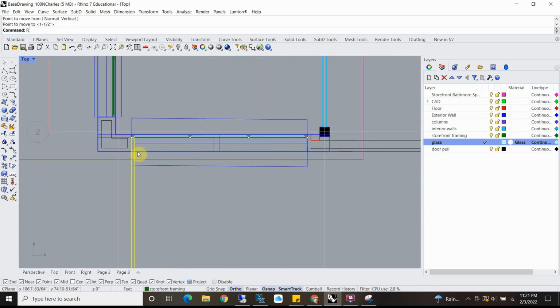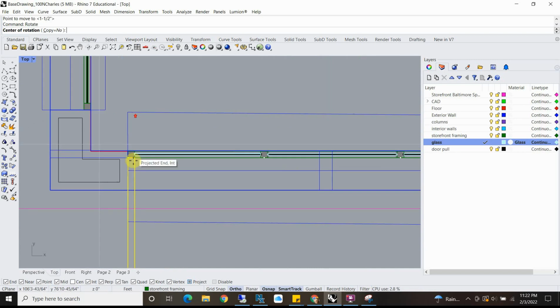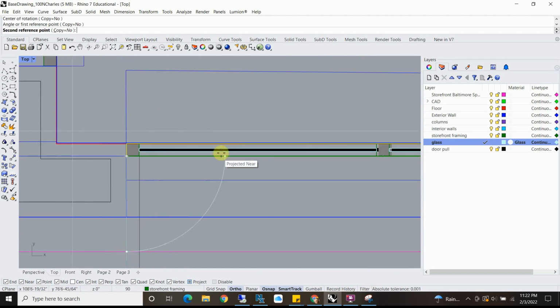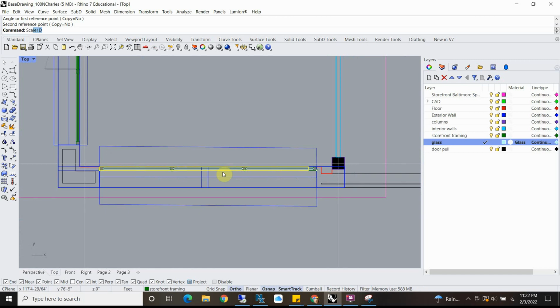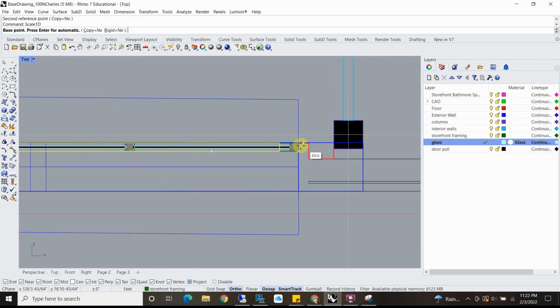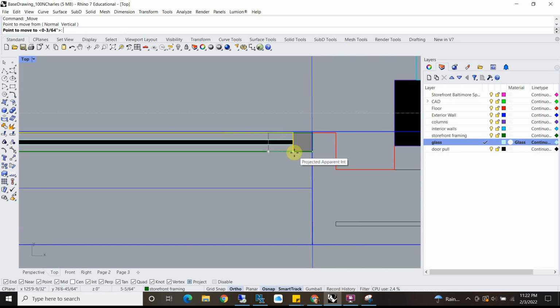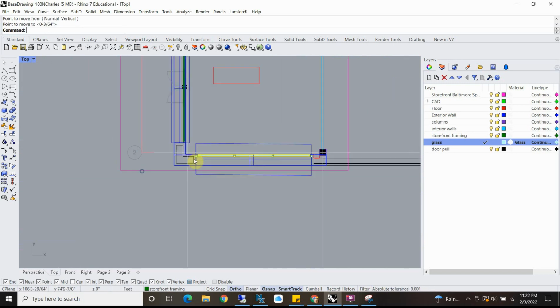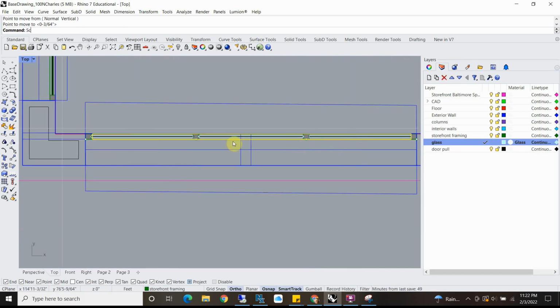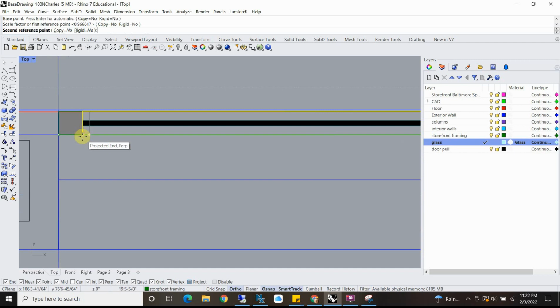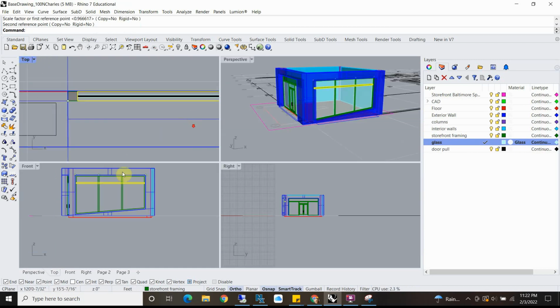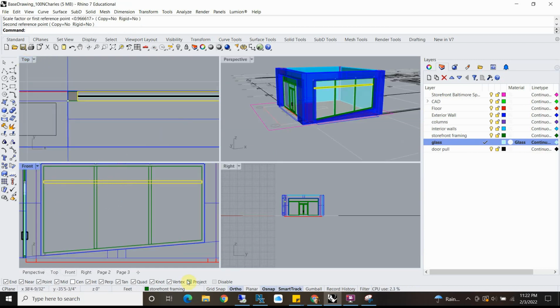And then I'm going to rotate it. I'm going to rotate from here this way 90 degrees so it lines up with that. I'm going to scale 1D. Actually, this might be the right size already. I'm going to move it to there. Let's see, how are we doing? It's close, so I'm going to do scale 1D. Click on this corner. Click on that corner. Click to there. Okay, so now that's in the right place.